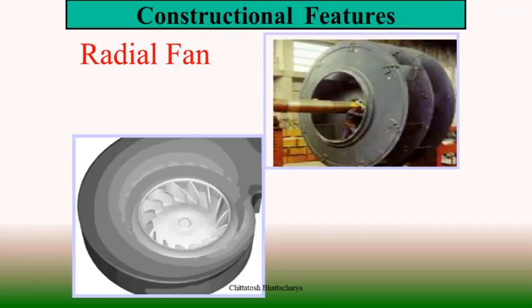Mostly they are found in riveting type of bolting arrangement, and the arrangement is covered in such a way that there is no erosion effect of loosening, and the shaft is fitted with the rotor through some key arrangement. Key slot is there, so that way they are connected. And in case of ID fans, the shroud rings are arranged in such a way that they can fit with the suction eye of the casing.